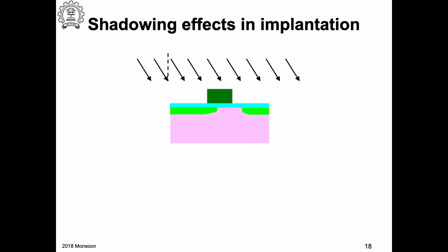And so there is no way I can get this voltage here unless short channel. But you forget it. So I am actually controlling this PN junction by applying a gate bias. You get the point? So that is why this is actually PN junction characteristic. This part. Source to channel junction.